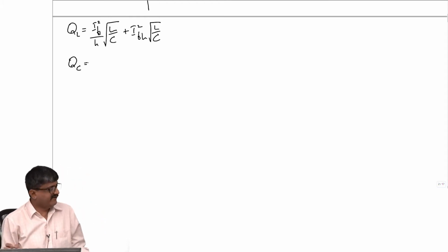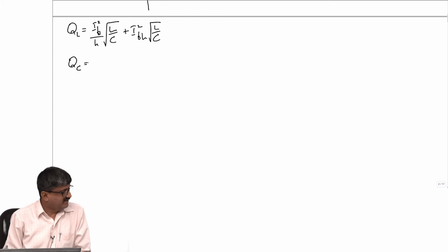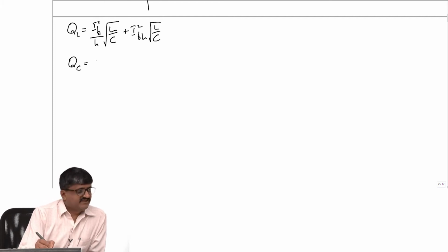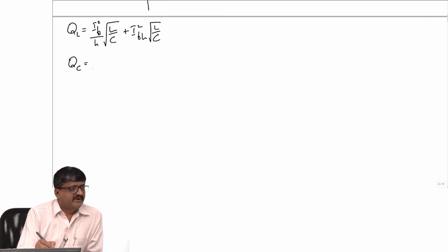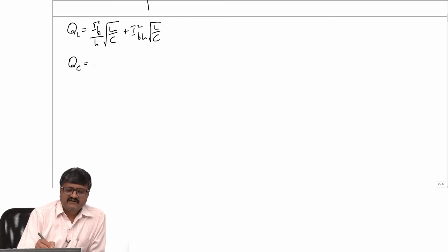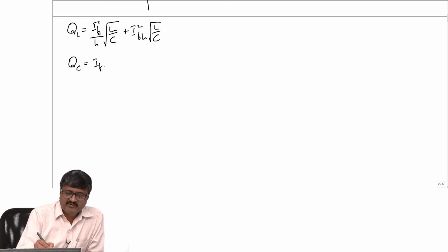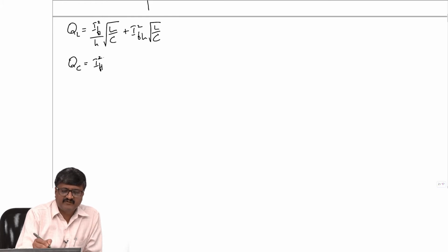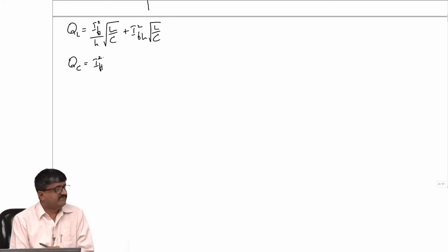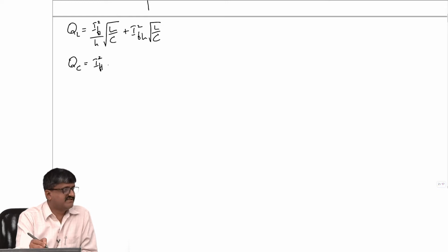Similarly, let us take the reactive power rating of the capacitor. If I just ignore all the harmonic components other than the harmonic component for which the filter is designed, then only the fundamental component of the current and the relevant harmonic component is to be considered. So, there is a reactive power rating due to the fundamental, that is IF1 squared into reactance. What is the reactance of the capacitor at the fundamental frequency?